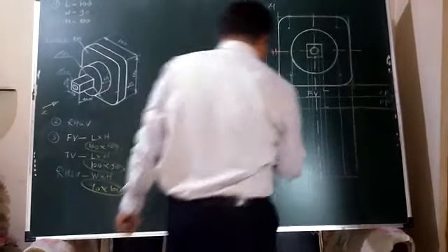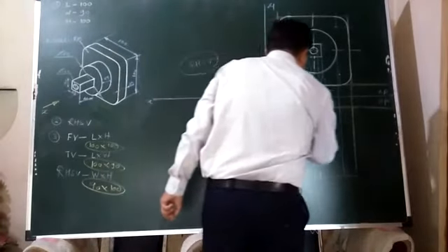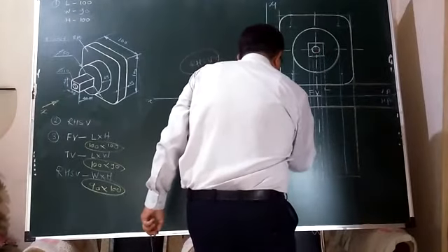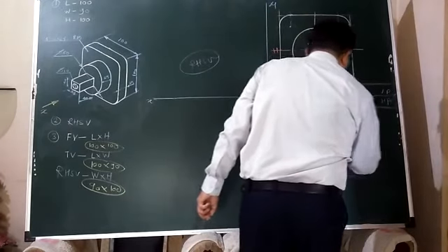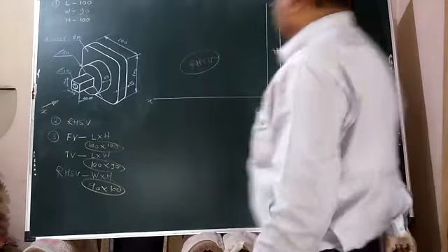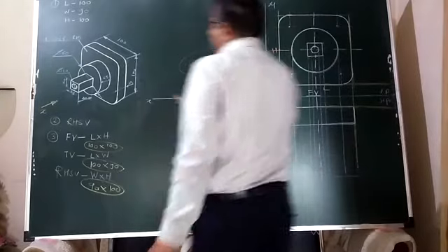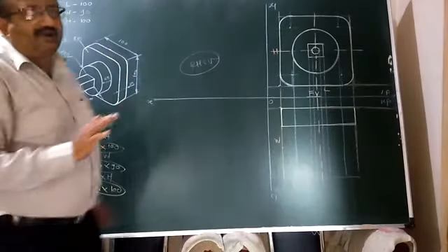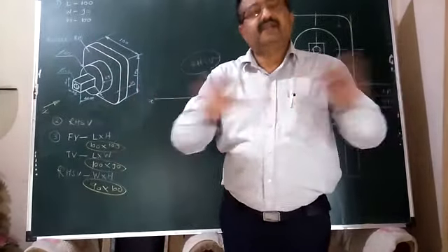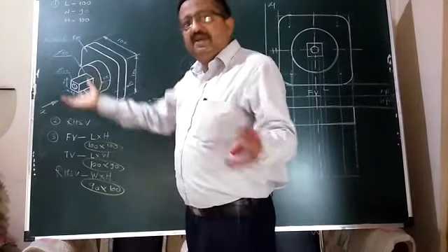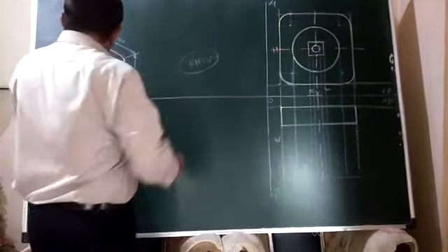Okay. Yes. So that strip now I will make it fair. Rectangular strip, length is 100 and width is 25. Width is 25, length is 100. It will appear. This curvature also will not be appearing in the top. All the curved parts, while observing from the top, will give just the strip effect, that is the rectangular effect. Those curvatures have appeared in the front view, that we have shown here. In the top view, only strips you have to show.